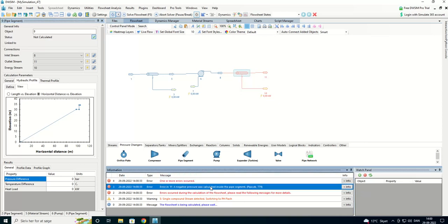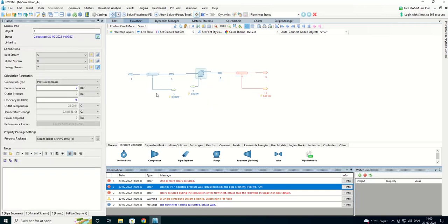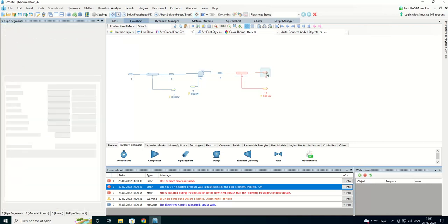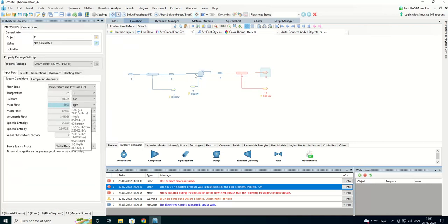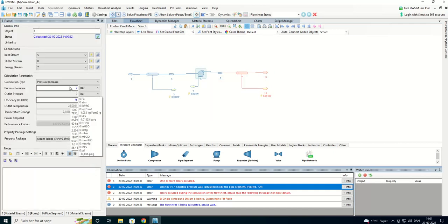We're getting a notice that we have a negative pressure. That means that our pump doesn't give any pressure. We don't have any indication of how low, but we are going 30 meters up. It's at minimum 3 bar.